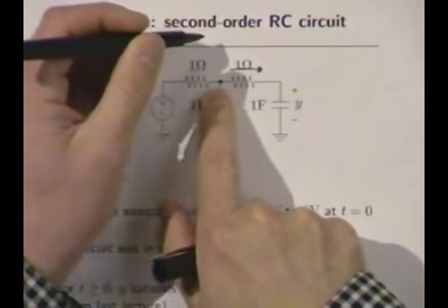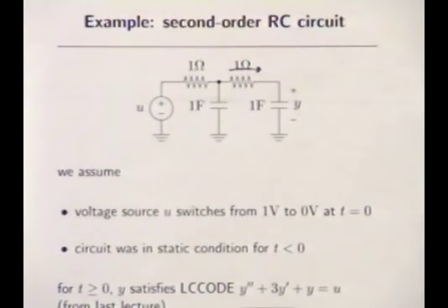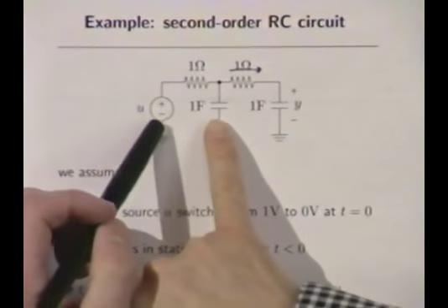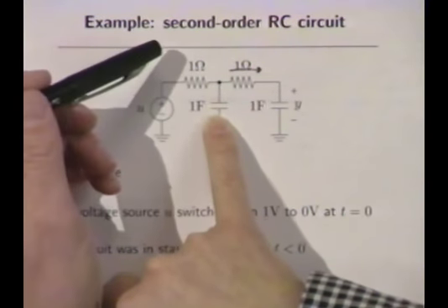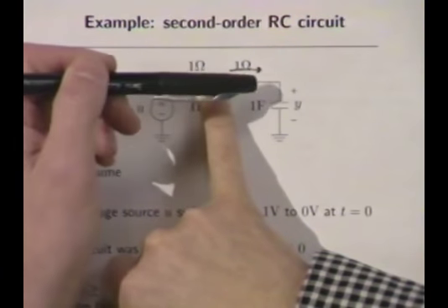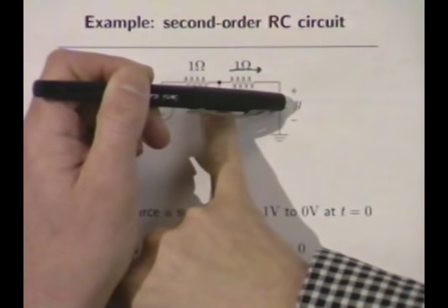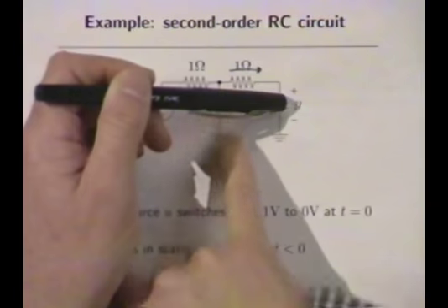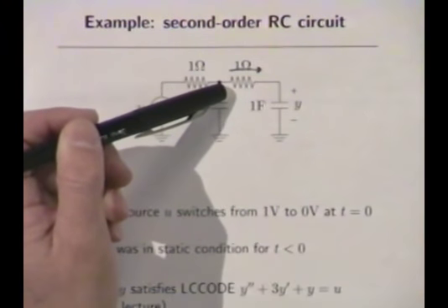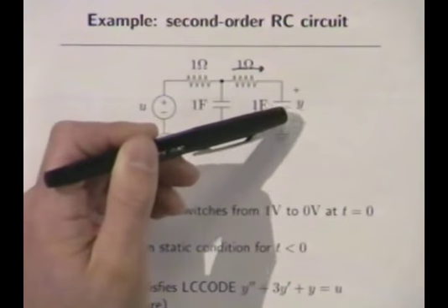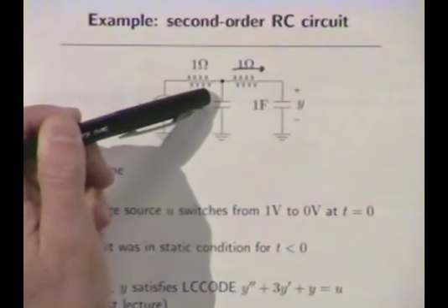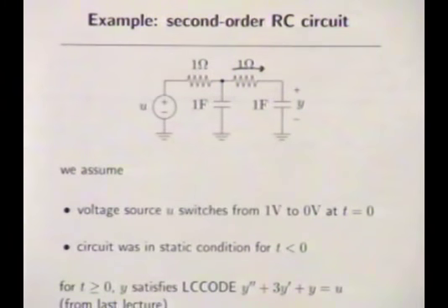and so on. So what happens now is it's kind of like various buckets of water and so forth. This thing goes up, a bunch of water pours into this one, and as the water level here rises, the leak to the second bucket kicks in. And so here's what we expect to happen. Both of these voltages kind of smoothly go up to 1 volt eventually. Okay? This one a bit slower than that one. Okay, so that's the intuitive analysis without any differential equations.